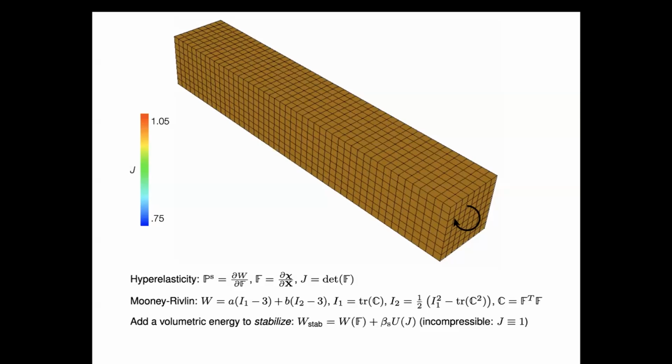That operation, even if the background grid velocity field is discretely divergence free, isn't guaranteed to maintain that property on the Lagrangian structural mesh, unless you set it up correctly, and I'll show you that in a minute. So there's no guarantee that the velocity field that you get on the structure is incompressible.